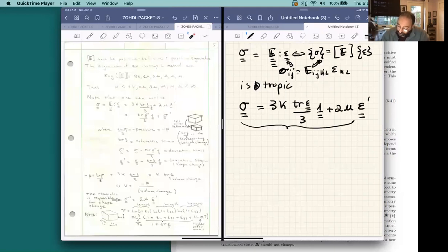Whenever we write the stored energy of the body as epsilon inner product with E inner product with epsilon, the reason being is that the stored energy is the product of the stress multiplied times the strain times a half. Again, go back to your notes and see exactly that representation at the beginning of the packet. Since this is greater than 0, since it's an energy, what is the implication of that statement?